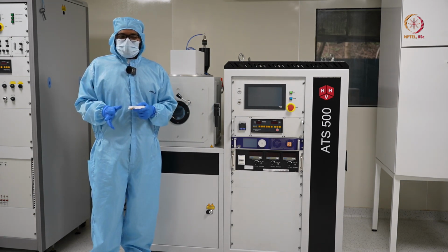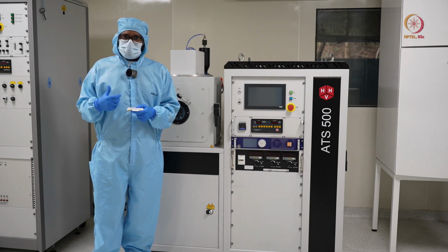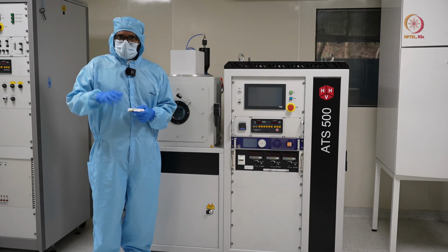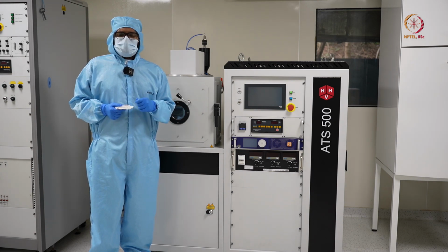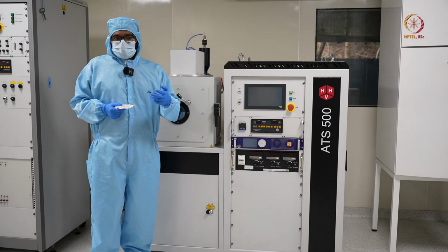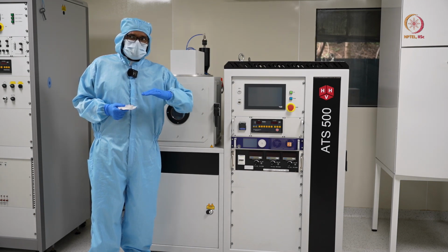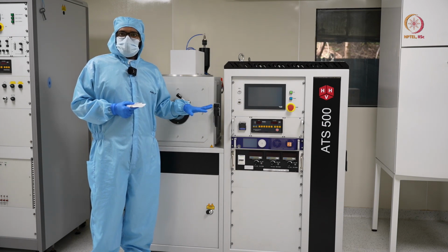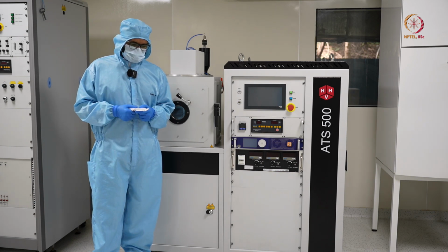The third trade-off is that when you are depositing using a thermal technique, the final film that you get is quite smooth. It might sound good, but in certain cases you might not want a smooth layer. Maybe your device or your requirement demands some roughness, maybe in nanometers. In that case also sputtering will be the go-to choice, because the final layer that you have after sputtering is not smooth.